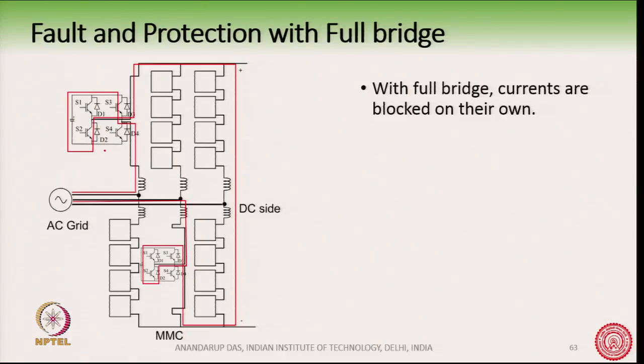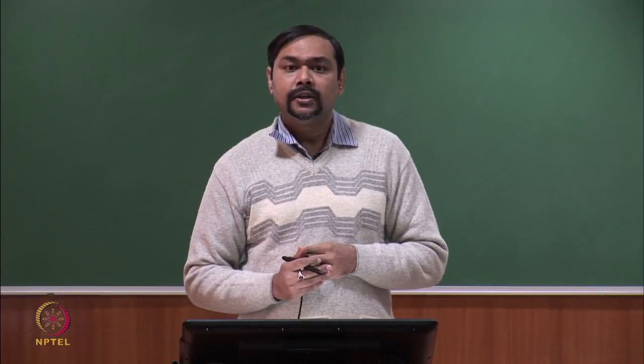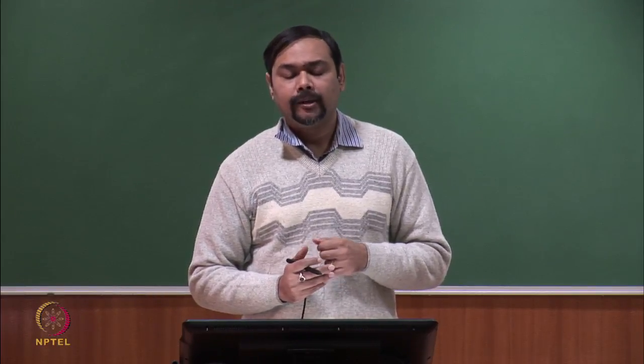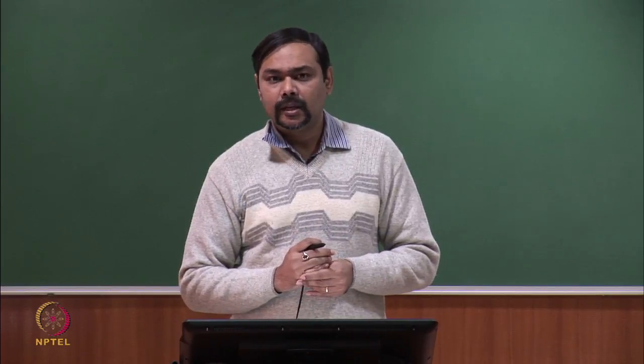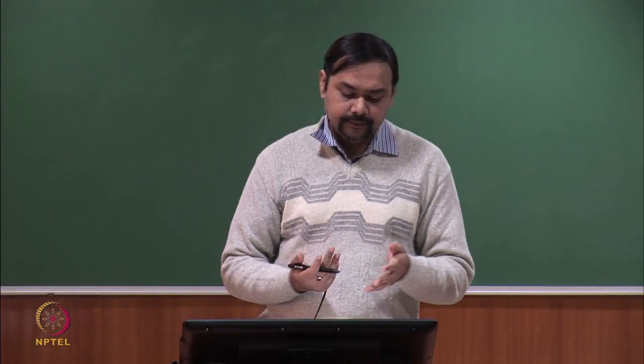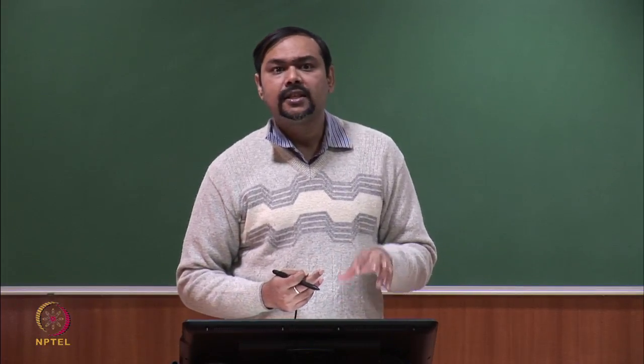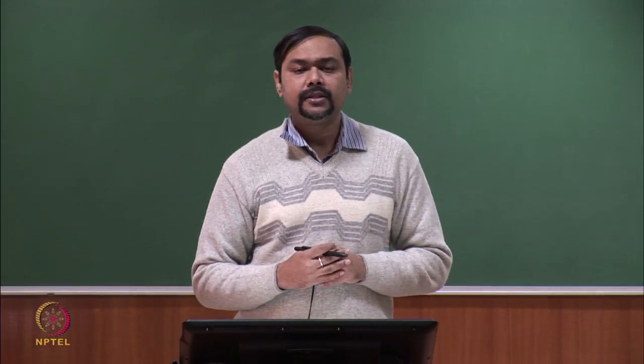A full bridge MMC circuit has a better performance than a half bridge MMC circuit during fault condition. So, many of the commercially established MMCs use full bridge instead of half bridge. Okay. Now, of course, in a full bridge circuit, as you can understand, the losses will be more, because instead of using 2 transistors, we are now using 4 transistors. The losses will be more, but the fault performance is much better in a full bridge circuit.